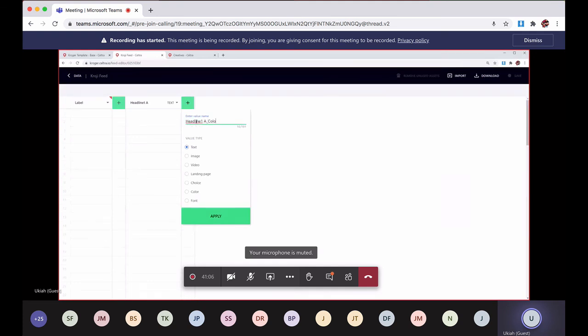underscore color. So this is super important and a huge efficiency actually. When you name something the same name as the attribute or the component in the creative, and then append this little suffix, underscore color, you can say now it's a color, and when I go to link them later, it will automatically link to that component.